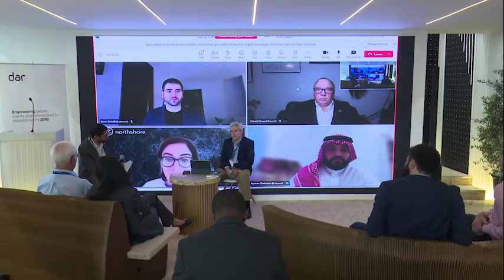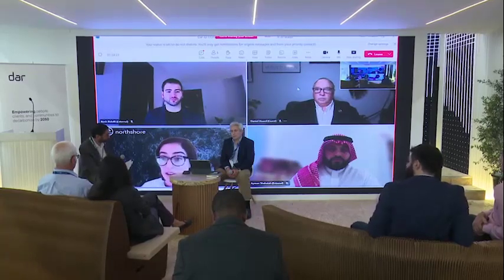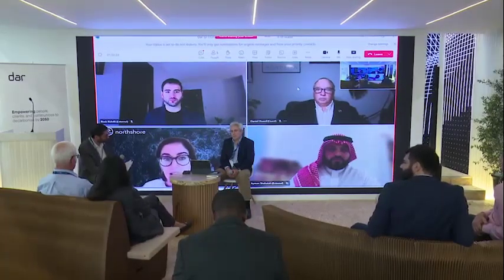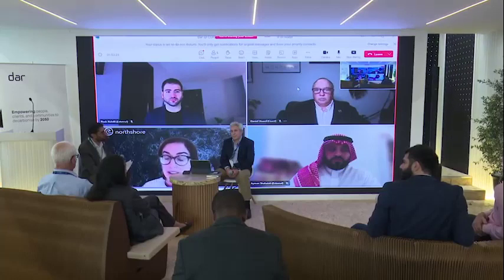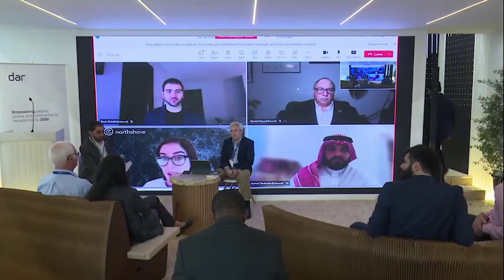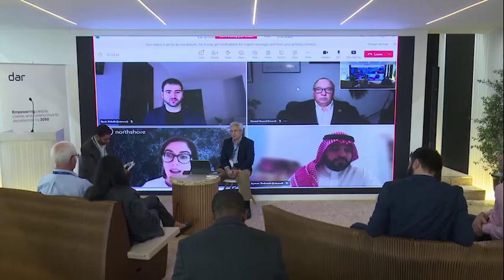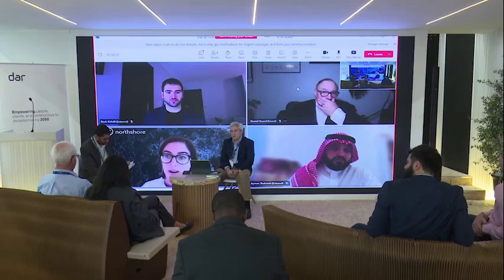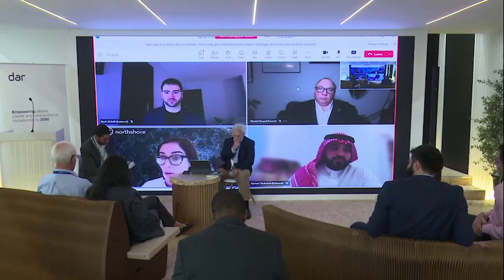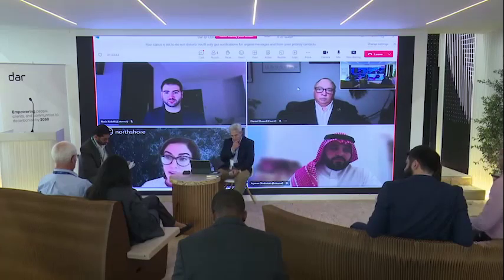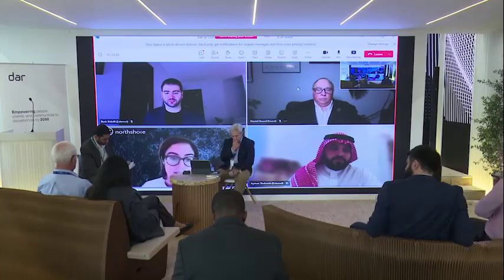So I think the first step would be to install smart meters. I'm working on a project now across a portfolio of data centers where we're doing that so that we can have real-time data. We connect it to our building management systems and see when we're using water, not just energy, but also water, and why, and what systems are associated with it. And then you can make informed choices about where to invest in water reduction strategies in your facility.